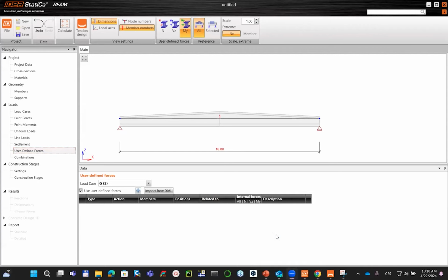Yeah, if there is another one, can mild steel reinforcement be based and perform checks considering it? For instance, for crack control or check ultimate limit state. Generally, the mild steel, you can change the properties of the rebars. I will show you where, and how it's reflected in the code check.